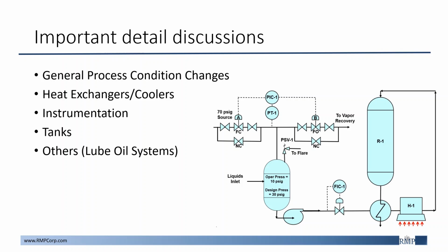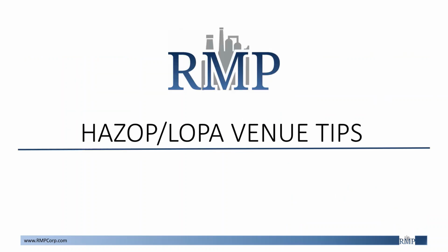Discussions on tanks may include vent locations and resulting hazards with them, tank maintenance and draining, materials of construction, as well as secondary containment, including draining requirements. The HAZOP facilitator should have the experience to understand how to request/prepare this information prior to the study and how long these discussions should last during the sessions to ensure that the progress of the study can be effectively maintained while still addressing these important discussion details.